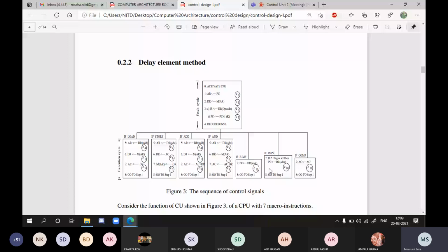Fetch means reading the memory for the opcode. So the opcode is always stored in the instruction register, you have to remember. Through the data register, it is stored into the instruction register, and whenever the processor executes any instruction, the program counter is automatically incremented, that means to the address of the next instruction. You know that the control unit is responsible for maintaining the sequence of instructions, how your program will be executed. Now these steps 1, 2, 3A and 3B are required for your fetch operation.